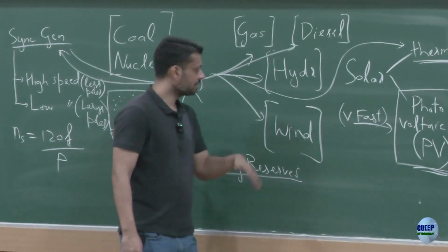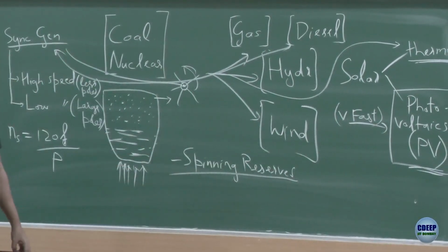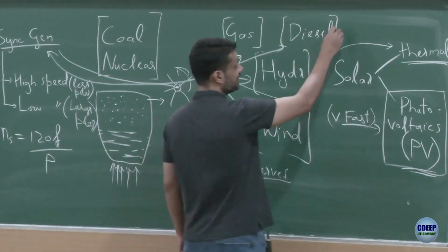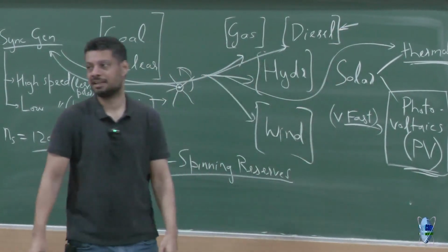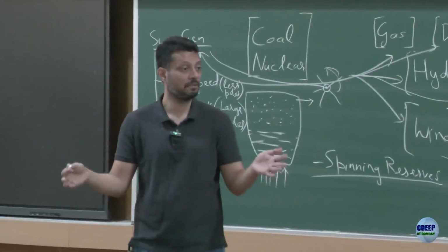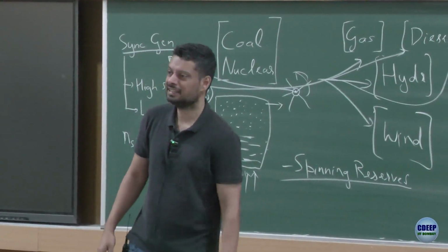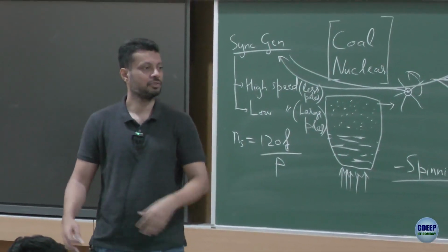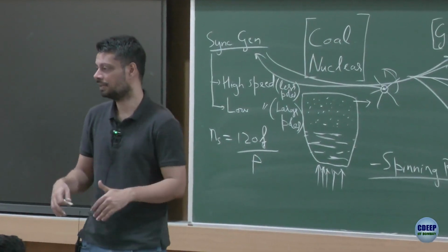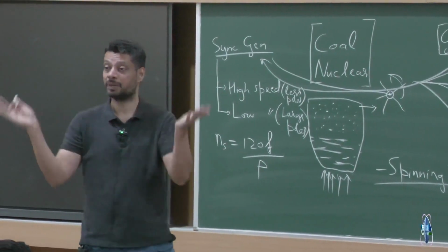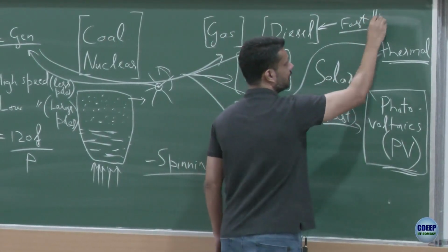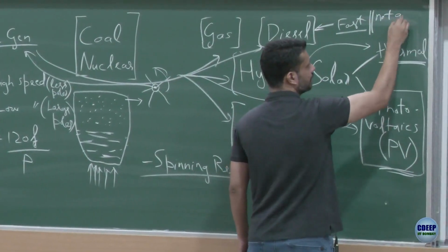Okay, what are the other ones relatively faster now? Diesel, yeah, press the button and then the engine starts, right? You can start diesel very fast, but the only problem with diesel is that it is not predominantly used for the bulk of power generation. So hardly any diesel would be synchronized to the grid. Diesel would mostly be used for remote areas where there is no grid. So you transport diesel, you run a DG set and get power, right? So these guys are usually not connected to the bigger grid. They are relatively, let us say, not very fast, but they are not grid connected.